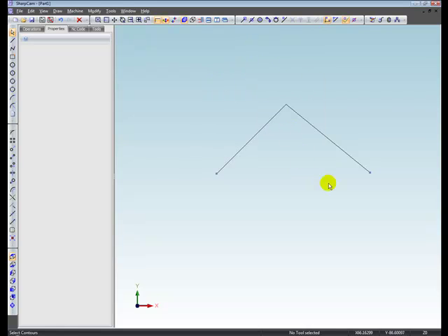Now we can see here, these two are connected. We can tell they're connected because at the end of the contour, which has two lines, we've got a purple dot. This is a connection marker. And purple signifies the ends of an open contour. Whereas if it was a closed contour, if that point matched that, then it would be orange in colour. And by the way, you can change the colours under the options dialog box if you want, but these are the defaults we're dealing with here.